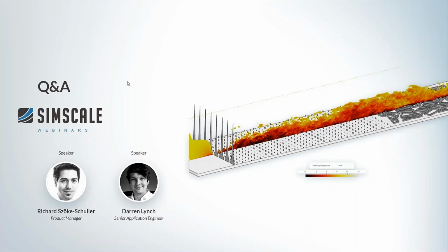So now we have a lot of questions. Let's get started. How is the inflow turbulence defined in the current case is the question. So we have seen several cases here. The case that Darren has shown in the live demo didn't have any roughness elements that you would have in a wind tunnel. So here we applied the turbulence profile with the height directly with the mean profile, also the velocity profile.